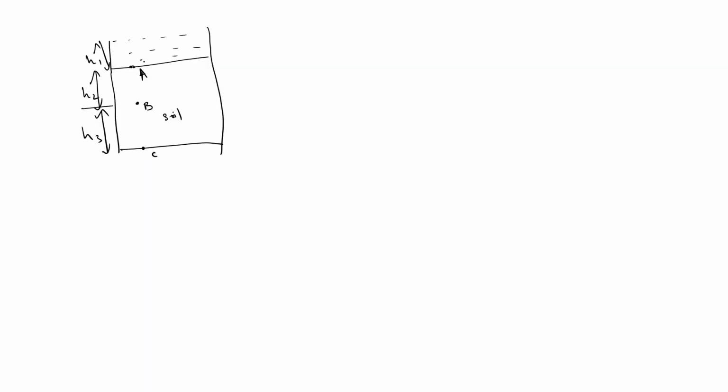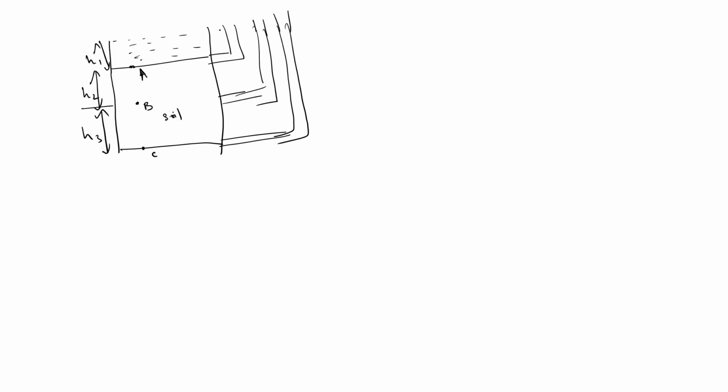So this is water and there is a pressure tube which is attached. Also at the point B it is attached, and at the point C which is at the bottom. Now as shown in the figure in the question, the water height which has come up into the pressure tube is of the same height, equal to this height. At every point we need to calculate effective stress, sigma A dash, sigma B dash and sigma C dash, and then sum them.